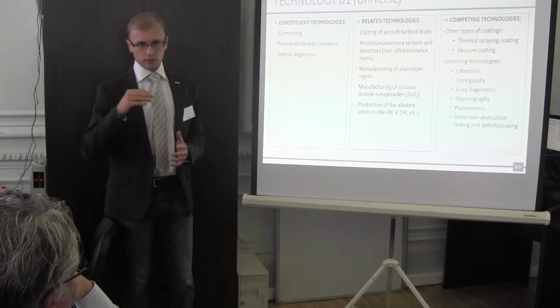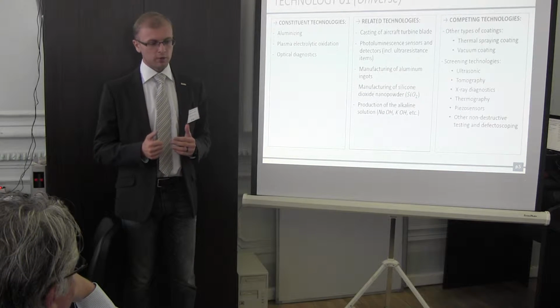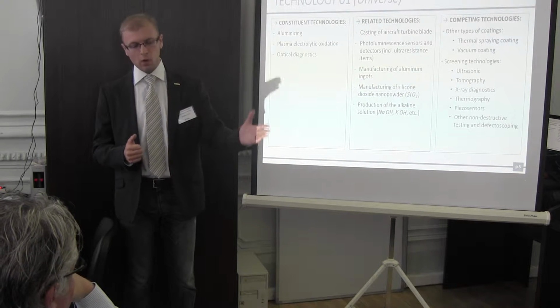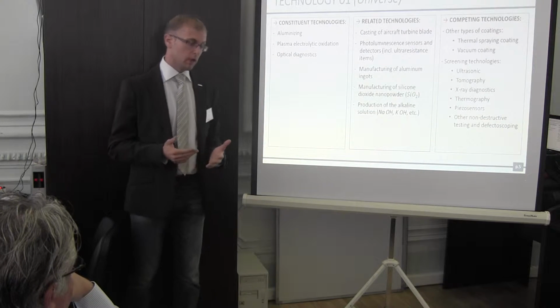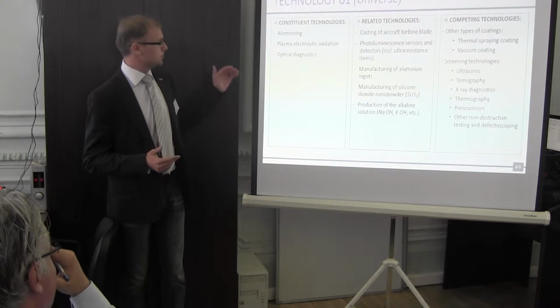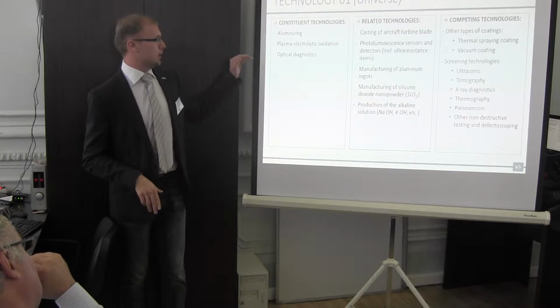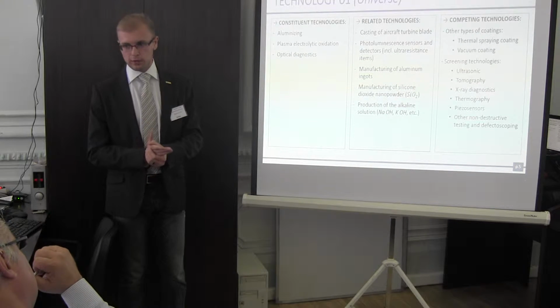We analyzed these articles and we tried to use the technological experience of our guys from our group, and we are planning to use the aluminizing of the blade and then plasma electrical oxidation of this blade,